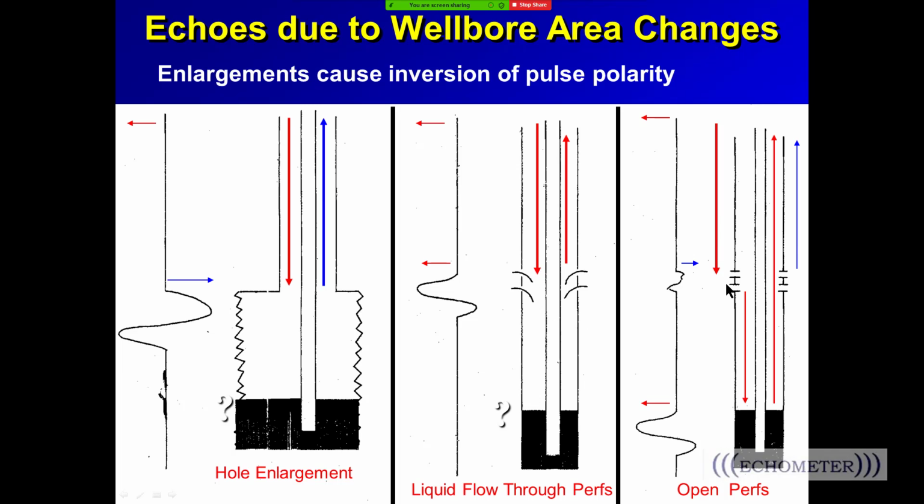Whenever you shoot a fluid level and you have an upper set of perforations, almost always, unless there's scale that plugs the perforation off, you see an upkick at the top perf. And so it's common to see the top perf kick, and the top perf is almost always a good downhole reference, a downhole marker. And then we see the liquid level below.